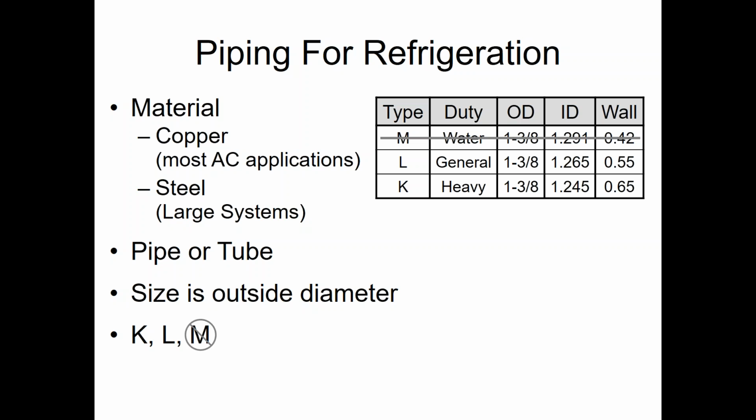Doug, did you say steel pipe needs to be nickeled or pickled? I couldn't understand what you said. Pickled, like you eat a pickle, kind of pickle. So for laymen like me, what does that mean? It's a pickling, it's a treatment of the steel to make sure it's clean and free of all debris, particulate. Just a way of treating the steel to make sure that it's clean and without particulate or debris on it.